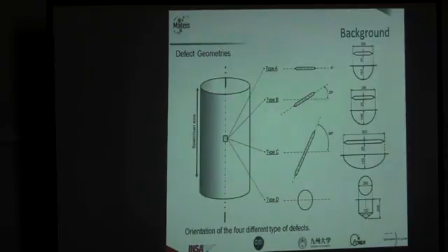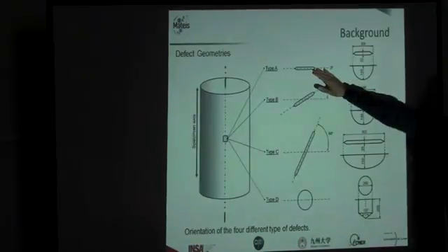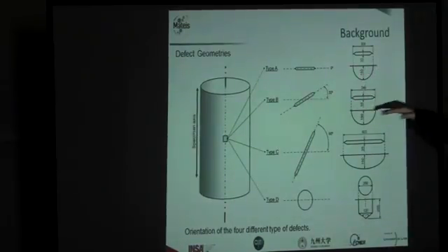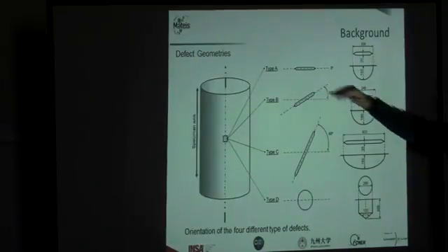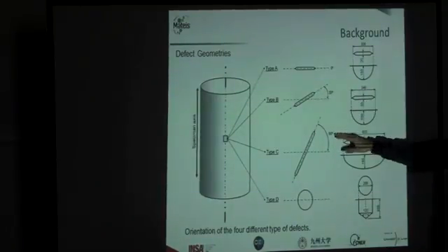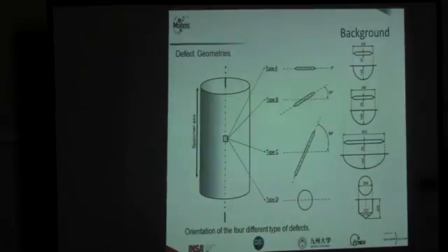These artificial defects were a semicircular slit at 0 degrees, a semi-elliptical slit at 30 degrees, and at 60 degrees. The idea is that if we project the area on the z-axis, we are going to have the same square root parameter, and then we did an extra, the typical Murakami's artificial defect by drilling, and the four of them have the same square root parameter.